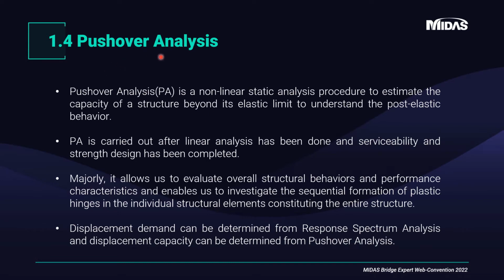So let's look in detail into pushover analysis. Pushover analysis is a nonlinear static analysis procedure that is used to determine the capacity of the structure beyond its elastic limit. So we try to understand the post-elastic behavior of the structure.